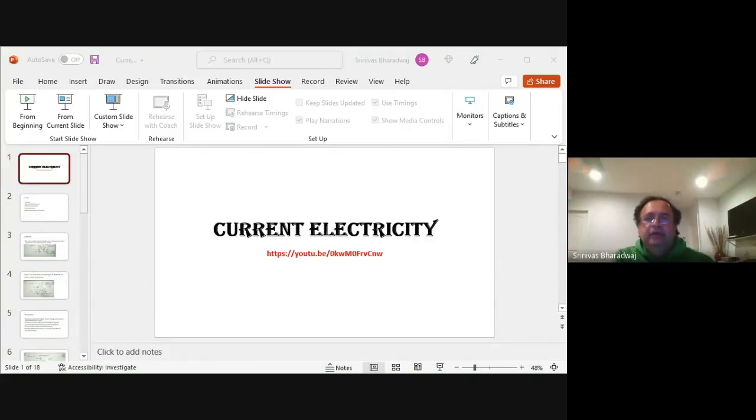If the third one was orange, 62 into 10 to the power of 3 is 6.2 kilohms, right? If it is red, they are saying 47 times 100, 4,700, 4.7 kilohms, right? So that's how you need to understand. You need to know which number each color represents.